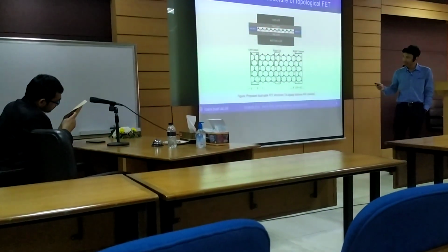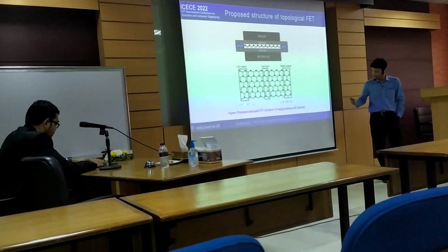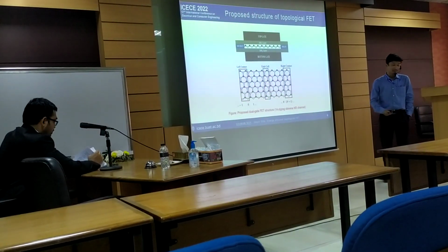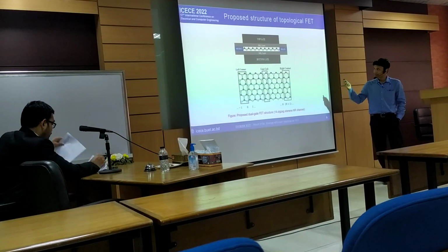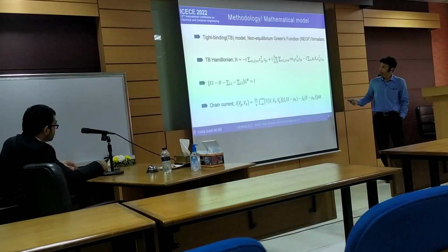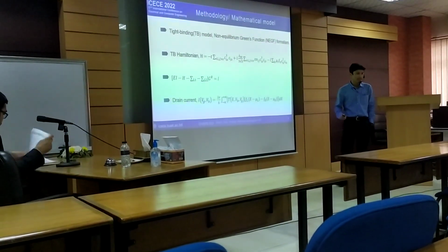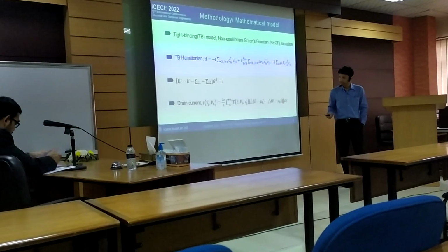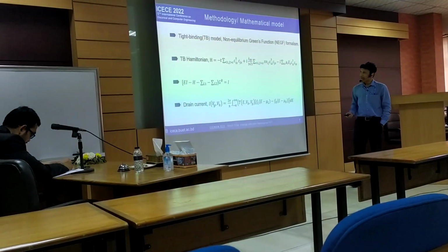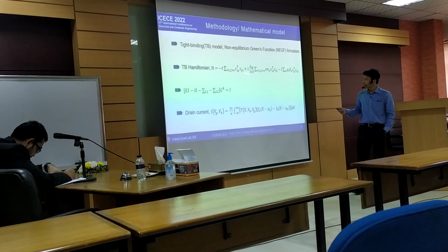But at this moment the main thing is that we have actually used the channel material as a stanene. And from the top view you can see the unit cells at the left and right leads, and the silicon dioxide as the dielectric layer. So we have actually used the tight-binding model and the non-equilibrium Green's function formalism for our transport equation and the transport calculation.